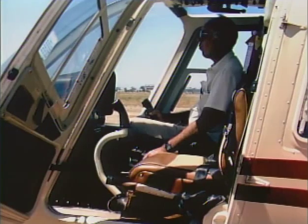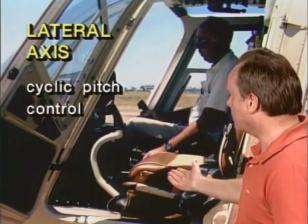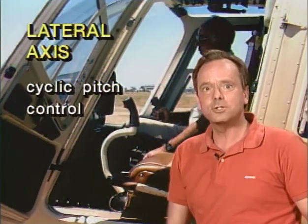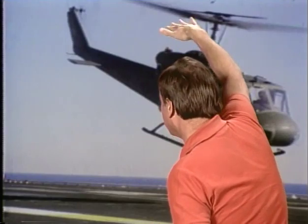Now, they also ask you, how do you control movement about the lateral axis? Well, that is pitch, and that also is controlled with the cyclic pitch control. So you do that by moving the cyclic fore and aft, and that changes the pitch of the helicopter. Now, they say, let's assume that you're in forward flight cruise configuration. How do you change direction of this helicopter? Well, the way you do that is by tilting the main rotor disc in the desired direction. The cyclic control really does it, but it tilts the main rotor disc in the desired direction.